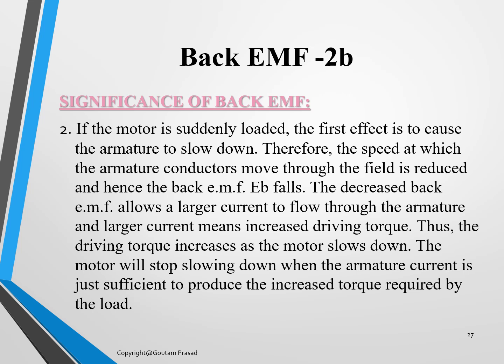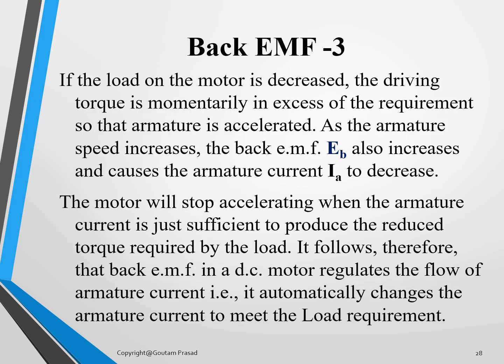Now, Eb is lowered, so the current is increased to increase the torque delivery that will help the motor to achieve higher speed, and thus the driving torque increases and the motor stops slowing down. The motor will stop slowing down when the armature current is just sufficient to produce the increased torque required by the load.